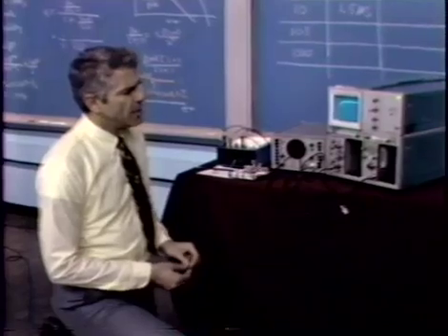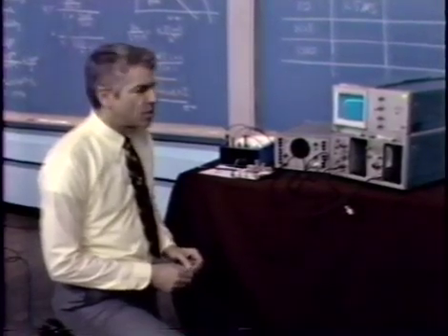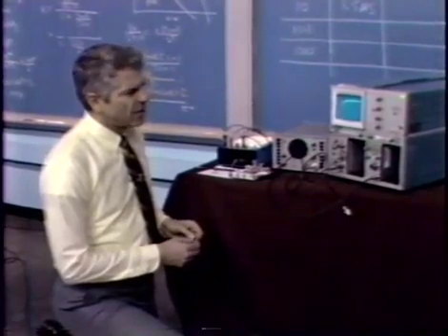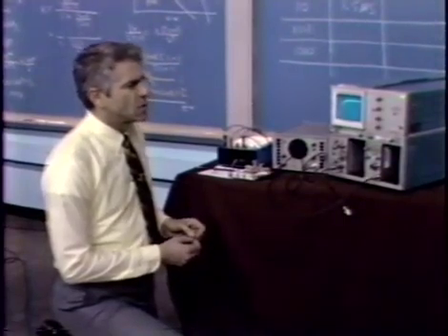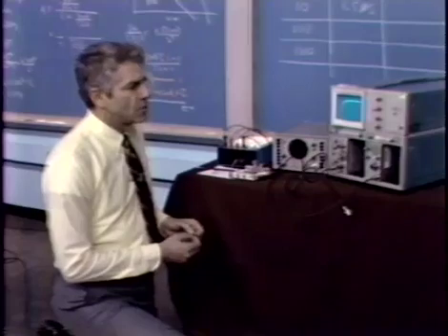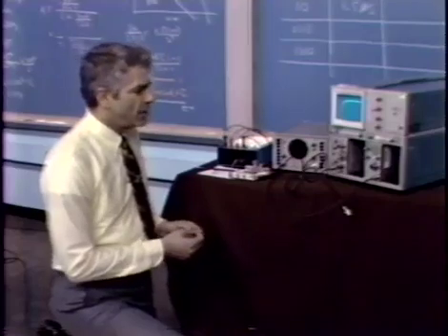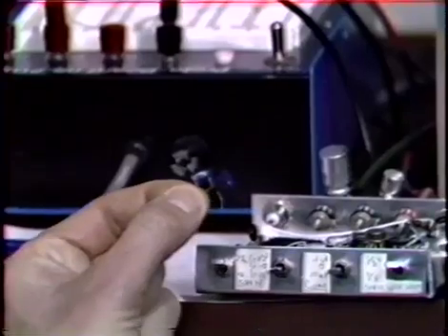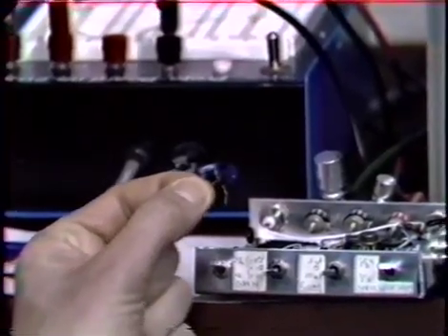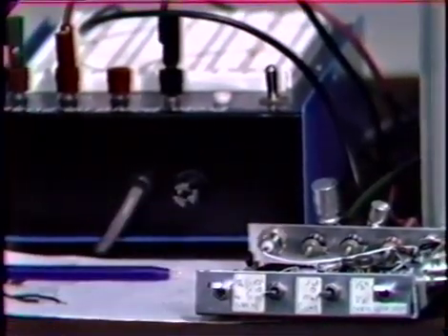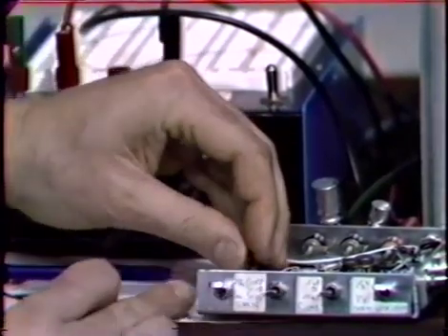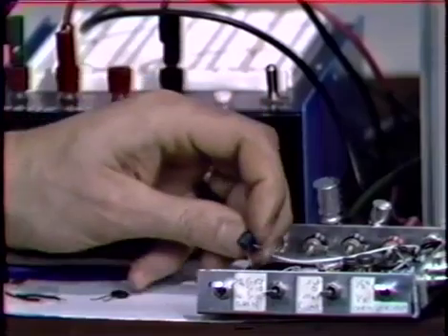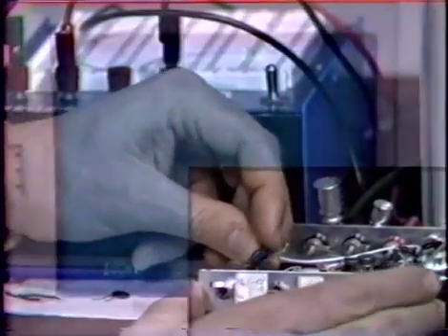There's a little bit of departure from the ideal case here. There are a couple of effects in the amplifier that actually force us to use a capacitor that's somewhat larger than 1/10 of the previous value. But we've made up a capacitor in that range, of about 3 picofarads or thereabouts. And we'll replace the compensating element with this lower value compensating capacitor.